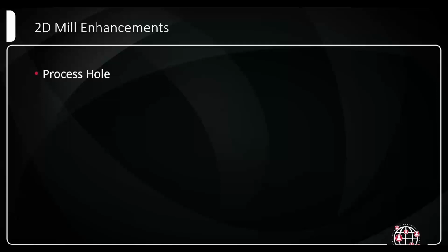Let's say I'm doing a tapping routine for a 1/2"-13. It can really be any part file you want. It could be just one of your normal job files, or you can make a template file that has a bunch of them. But essentially, you would pick a hole that's sized for that job. Then you would program the spot drill, program the tap drill, and then program the tap. And you have it all in one toolpath group, essentially. You save that file, and then this is where my video picks up.